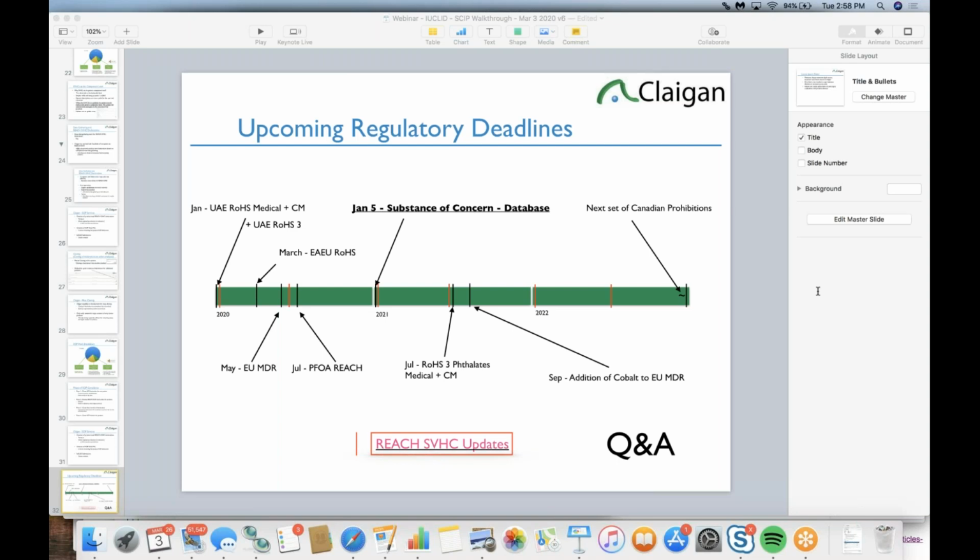So lead is an SVHC if it's in a metal or metal alloy. So lead is reportable. Lead in brass is reportable. Lead in aluminum is reportable. Lead in steel is, so all those 6A, B, and C RoHS exemptions are all reportable. Lead in glass is not. It's leaded glass, a different CAS number. So, for example, your thick film resistors will have a leaded glass layer, sometimes listed as lead oxide, but it's actually been agreed upon as leaded glass and not declarable.